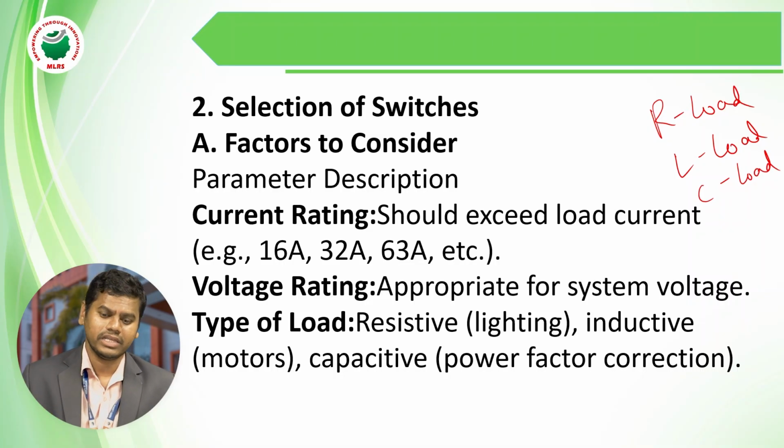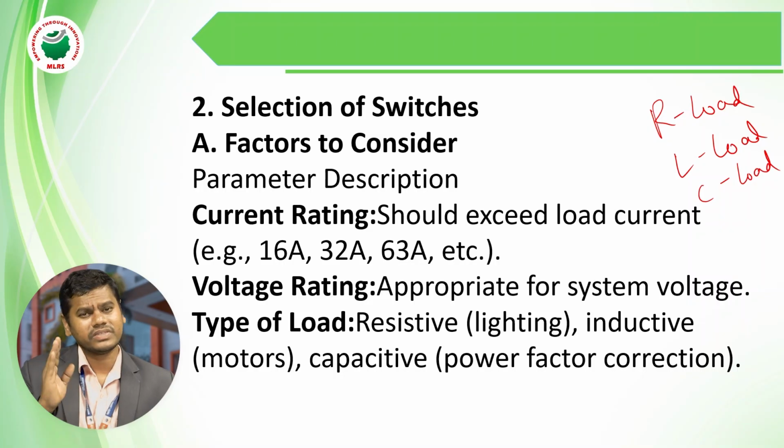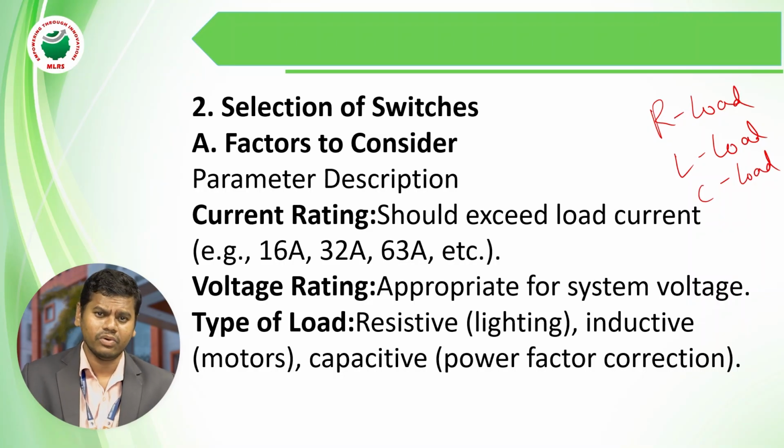The voltage rating should be appropriate for the system voltage, single phase or three phase: single phase 230 volts and three phase 415 volts. So this is the voltage rating.